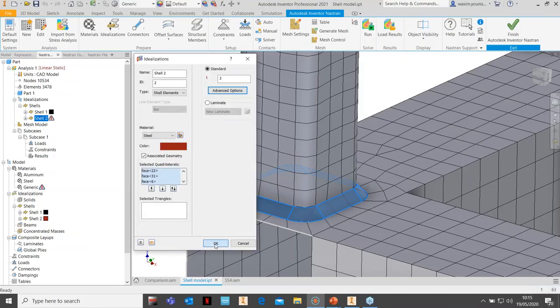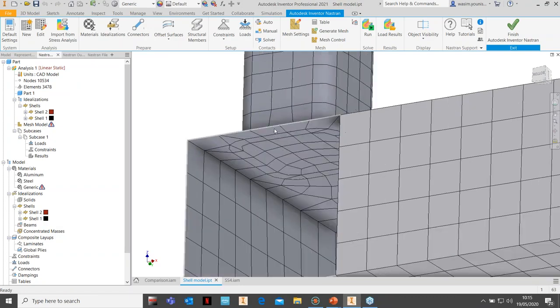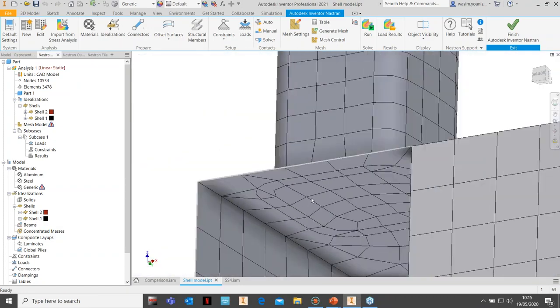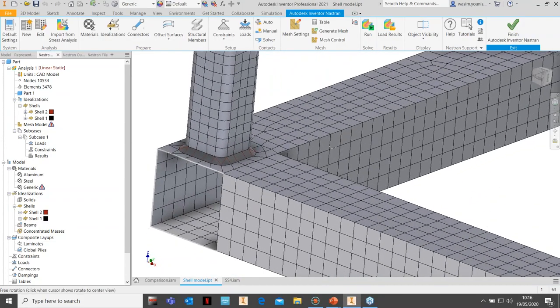Now, that's fine, but you have to be aware that that box section is in contact here as well. So you actually get extra stiffness, so you have to be aware of that. So you can see straight away, adding fillets or adding welds can actually create more work, and the real question becomes, is it actually worth the effort to get accurate results? So these are the workflows you have to consider within the Autodesk portfolio.